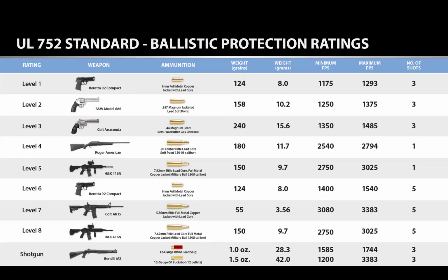And that brings my second point I want to point out about UL 752. They mandate that you mark off 15 feet before you discharge any weapon with any projectile at any surface of any material. This is not just pertaining to glass. So essentially, if your clients ever ask you, is there any testing between 0 to 15 feet? Unfortunately, the answer is no. And the reason they move you back 15 feet before you test these types of windows or doors is essentially that it allows the projectile to achieve its maximum velocity before it hits the surface of the materials as well, all right?